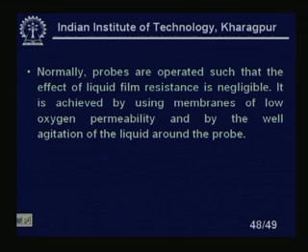Normally, probes are operated such that the effect of liquid film resistance is negligible. It is achieved by using a membrane of low oxygen permeability and by good agitation of the liquid around the probe. Okay. So, there is all this compromise we have to make.